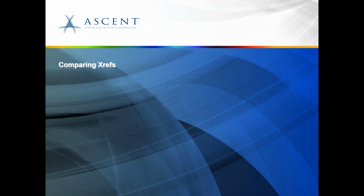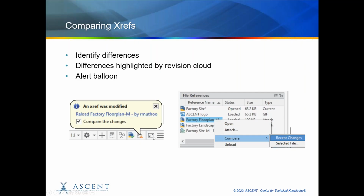So what it does is, when a drawing that is referenced inside another drawing is changed, you can see the differences between the drawings by using the compare Xref command. If the host drawing is open and the externally referenced drawing is changed by someone, you are alerted by a balloon. Here you can see that the balloon alerts you, and it says that this drawing was changed by somebody, by RM2, that's me. And when you click on the link, it will compare the changes.